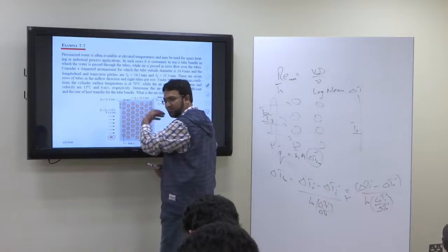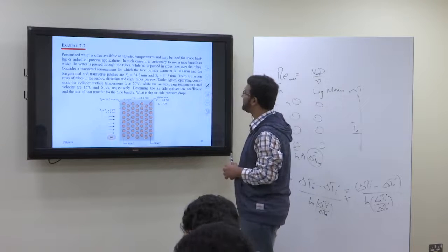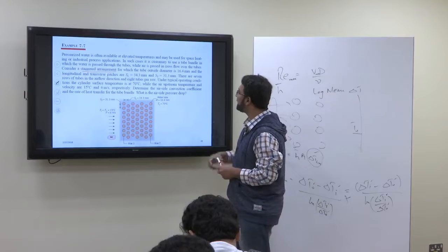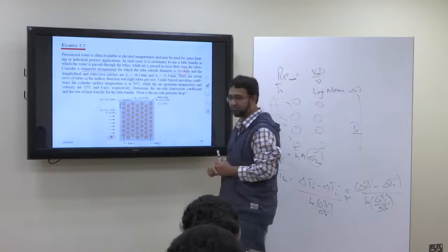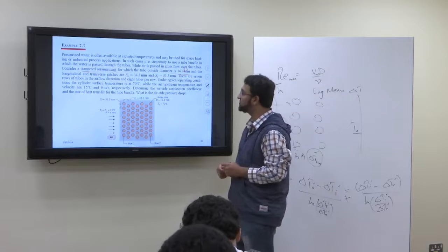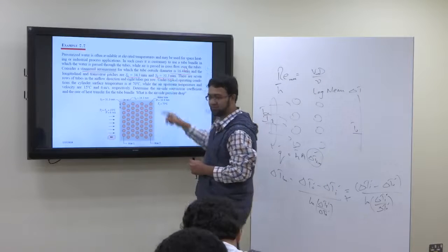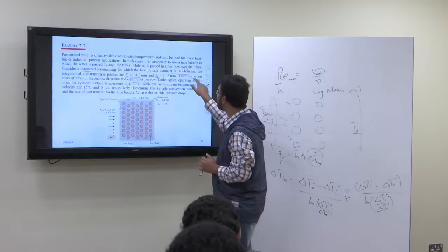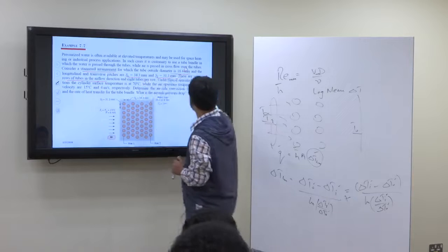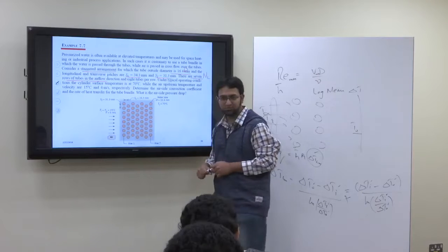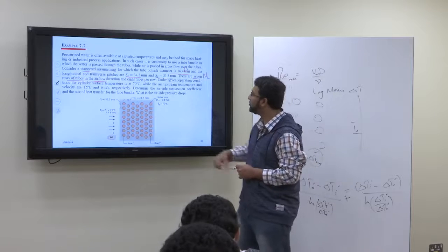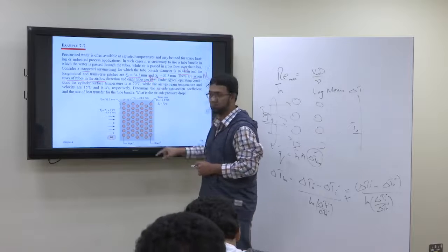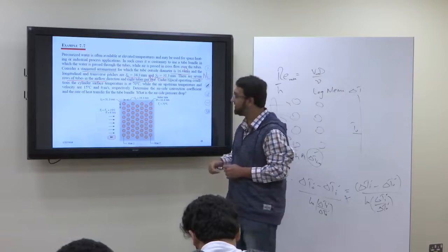So in the cross flow condition, we have the air. In cross flow over the tubes, consider a staggered arrangement for which the tube outside diameter D is given, and the longitudinal and transverse pitches, SL and ST, are given. There are 7 rows of tubes in the airflow direction, so this is NL, number of tube rows, and 8 tubes per row. This will be NT, number of tubes per row. NL is number of tube rows.